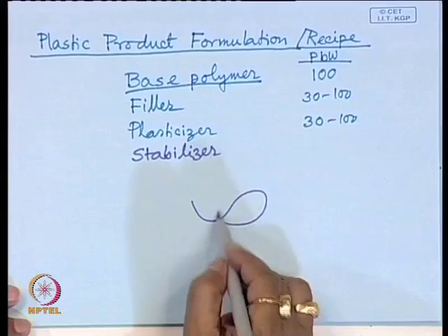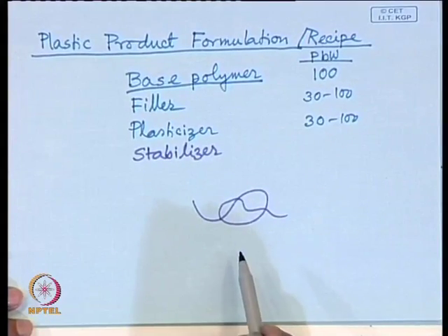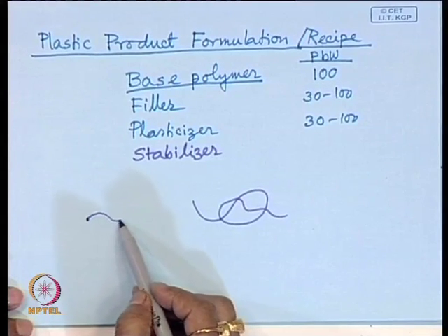So, availability of free space in polyethylene is less, whereas if you take natural rubber, and look into the configuration of natural rubber molecules and compare with that of polyethylene molecule, you will find in natural rubber molecule there is this kind of chain folding, whereas in case of polyethylene the extent of chain folding is quite less.